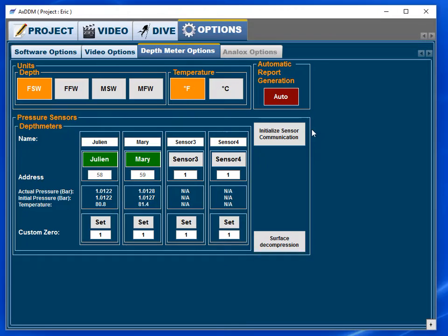Analogs will be for the SDA analyzer only. You can link a device, and so you can trend the value, the PV, the present value of the sensor, the output, and set limits, alarm, warning level, and high level alarm, and low level same thing. So if you trend outside the limit, it will just show an alarm, and it will record everything as well, the raw data plus the graphics.